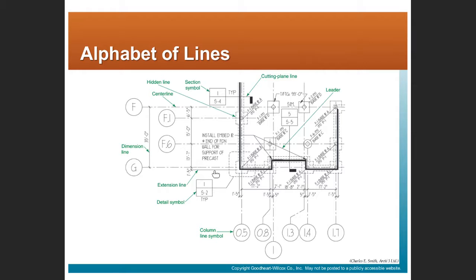Yeah, this 1 foot 5 appears to be the dimension between this corner of the structure and the center line of this row of footings, right? Because remember, the style of that line differs from the style of the extension line, which differs from the center line just above it.